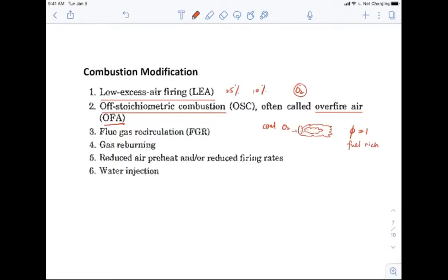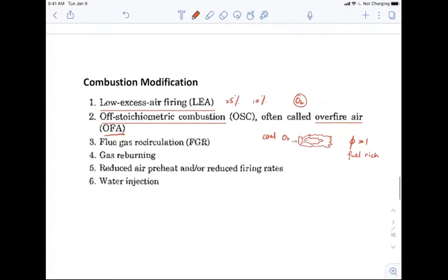So to save the energy of the unburned coal, what we're going to do is introduce another nozzle, okay, to just provide the air. That's why it's called the overfire air, okay? The air here is over the fire so that the extra air can burn all of those unburned coal or the hydrocarbon in the coal. Right. So in this way, you can still extract all the energy that's coming out of the coal, but at the same time, you reduce the temperature in this region. You also reduce the oxygen in this flame region so that you can reduce the NOx formation.